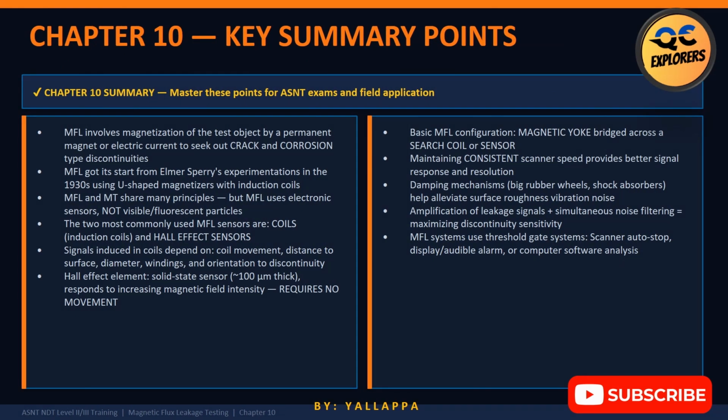Now we've reached the chapter summary. This is your high-value revision slide. Now pay very close attention here. This slide condenses the entire chapter into core memory points. First, MFL works by magnetizing a test object using either permanent magnets or electric current. Second, it is designed mainly to detect cracks, corrosion, and metal loss, but only in ferromagnetic materials.